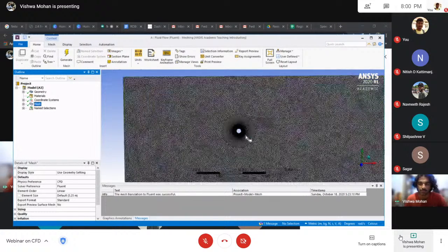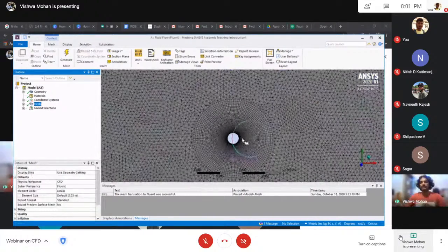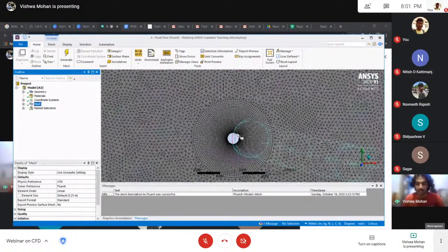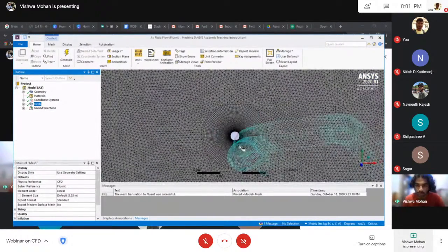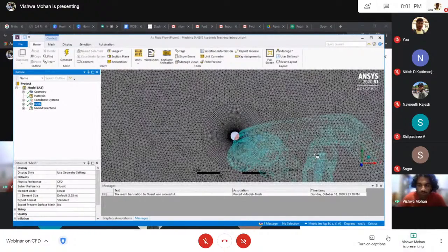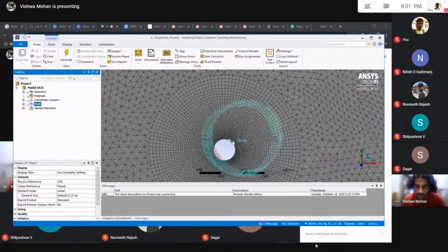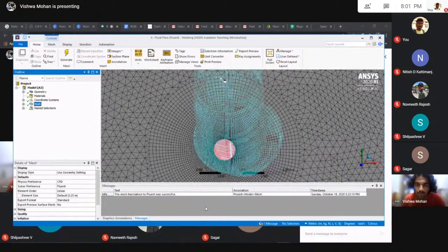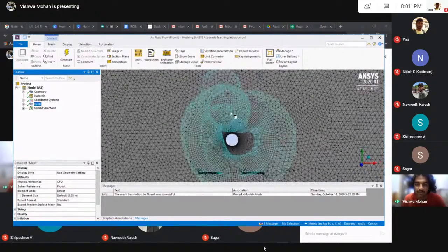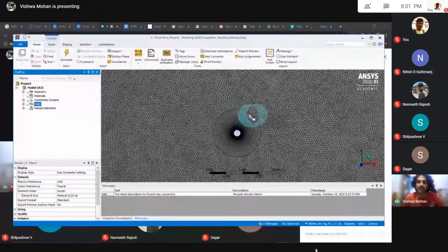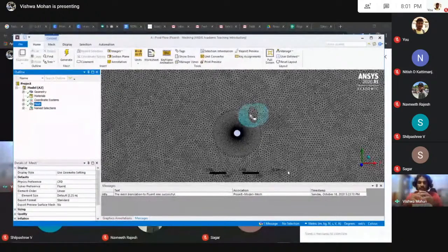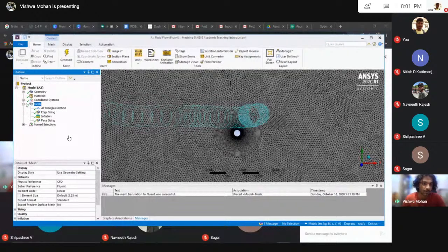This is my mesh. I was talking about a lot of things like mesh refining and other things. Yeah, they are very important. If you look at my mesh, you'll see that near this part, it's really dense, and it's kind of growing in a circle. That is the part that is called inflation, or inflating a layer. So how it's done.